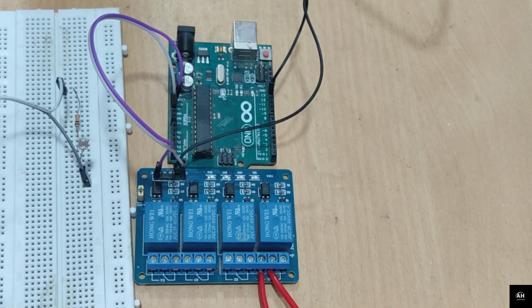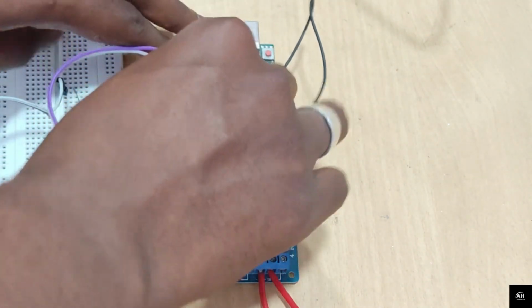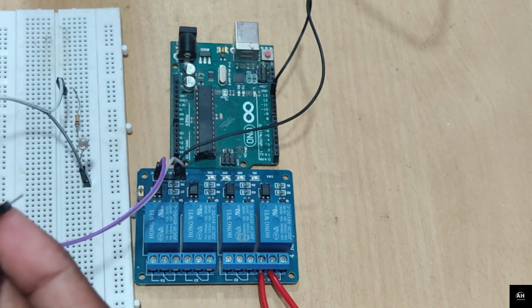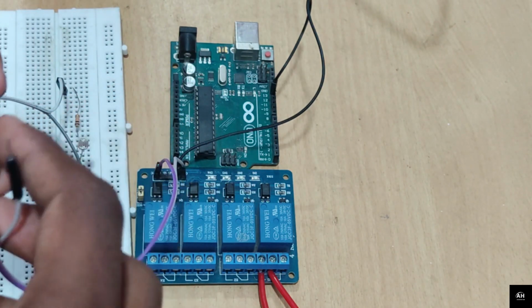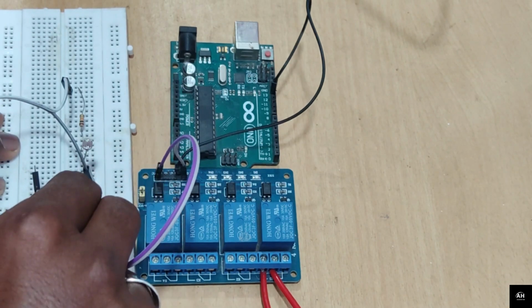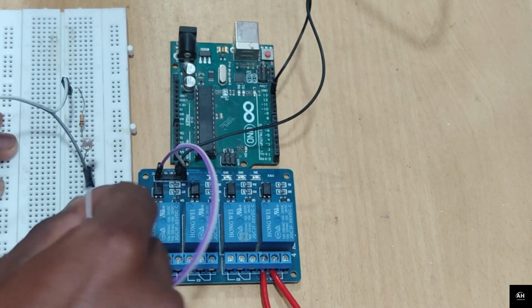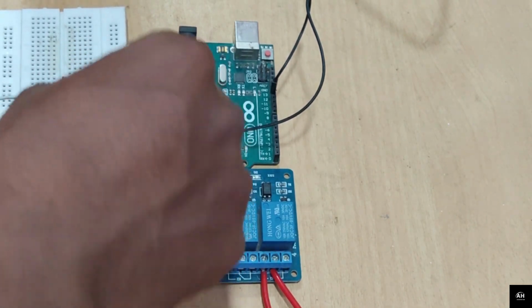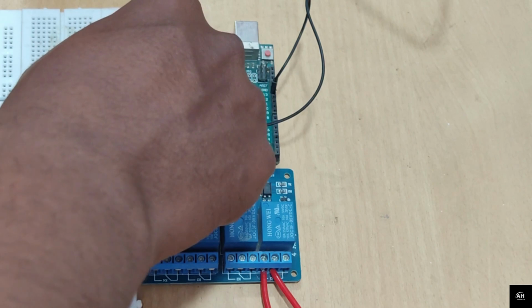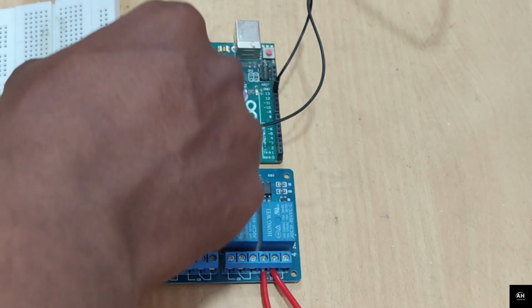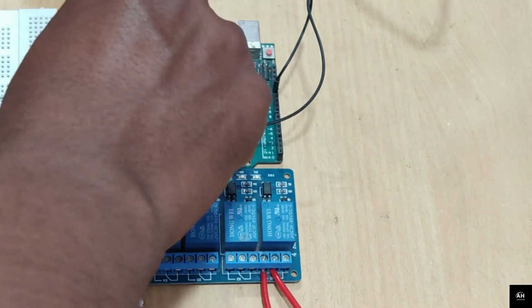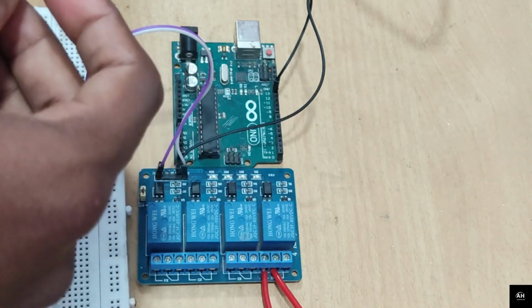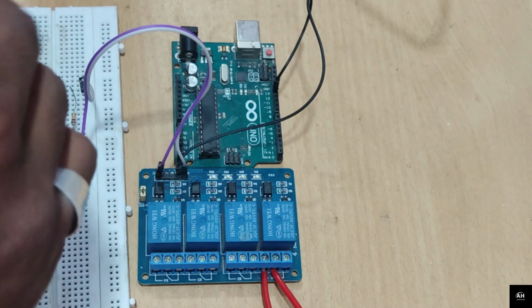Once we are done with it, we will remove the pins from our Arduino board for our relay module, and we will connect the 5 volt of the relay module with the LDR sensor's extension, where we have extended the 5 volt, and the ground will go into the extension of the resistor where we have extended the ground pin. I will connect it here, and after that we will connect these two pins to the ground and the 5 volt of the Arduino board.